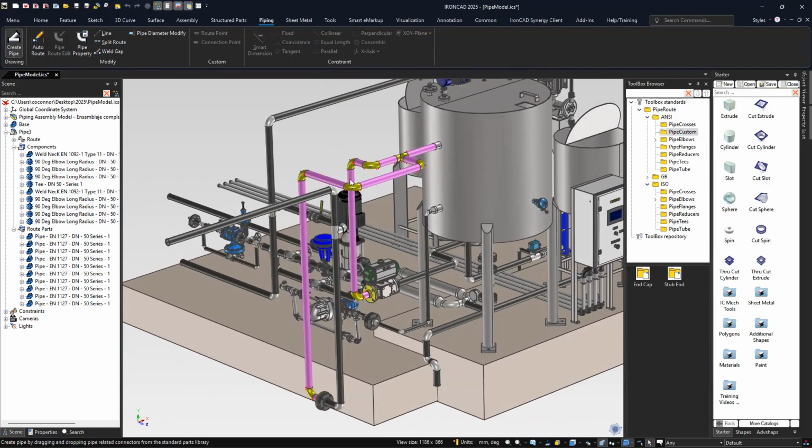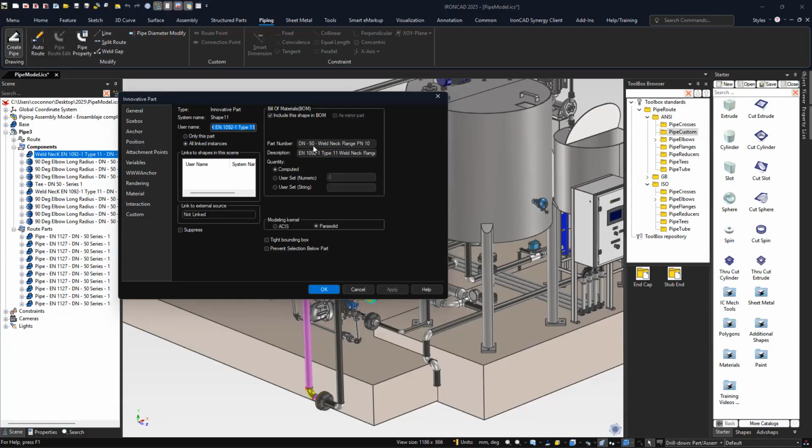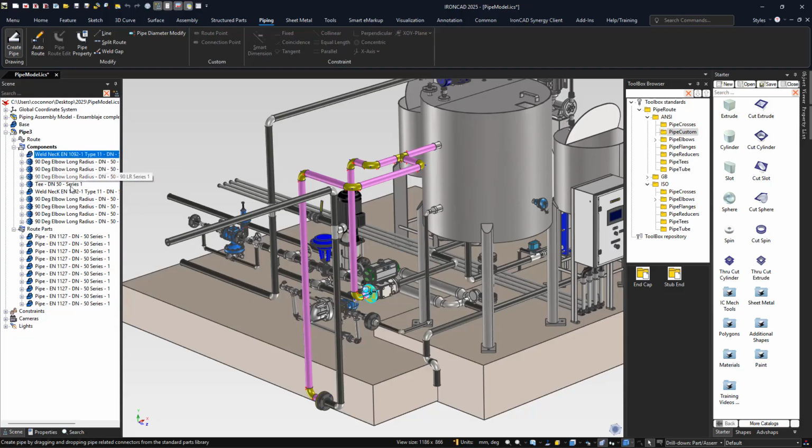And again, this can be created into the drawing. The bill of material will be created for all your components. And a lot of these components already have some naming conventions inside of here. If you look at the part properties, it's using formulas to pull parameter information, like the parameter that you picked for the DN inside of there. And also maybe the pipe type in some of these cases, for your pipes and your elbows. It'll pick those series as well.